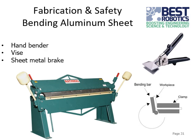Sometimes you may want to bend pieces of aluminum. So they have special bending tools. You can use the sheet metal brake. Here is the big thing shown there. That gives you a nice edge to bend along, and it can help you with the bend. They have hand bending pieces, but also a vise can work really well for that.